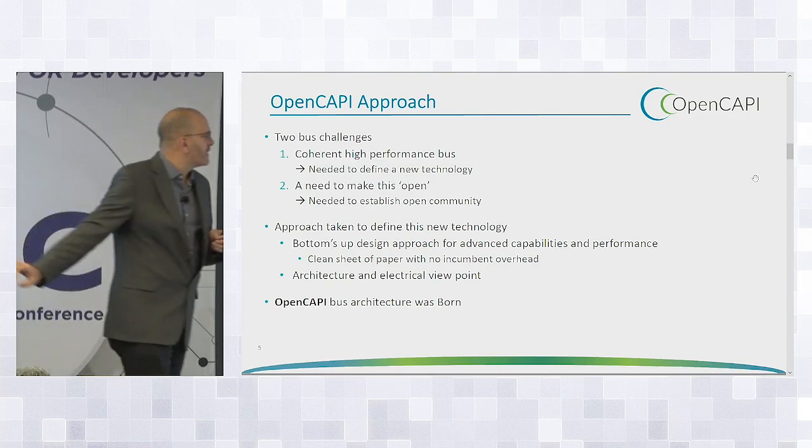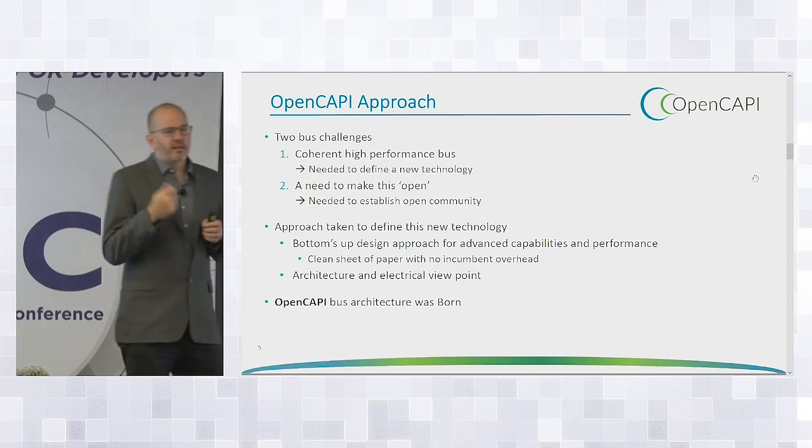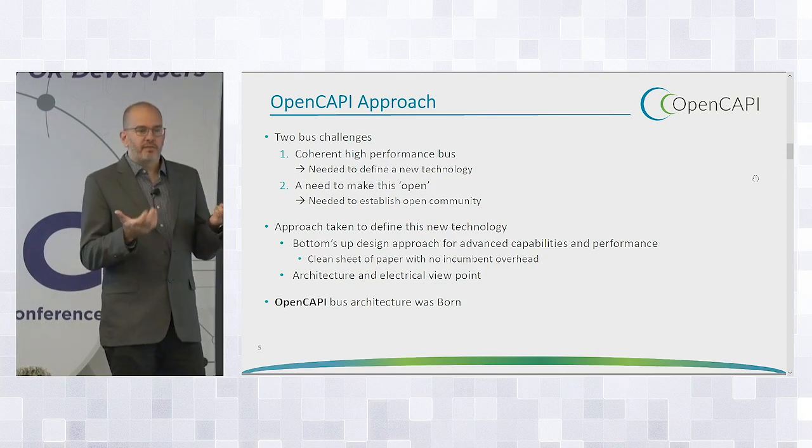The one interesting point though, just a side note, is the electrical standard with PCIe is actually fairly reasonable. It's a differential signaling interface. It runs at fairly high frequencies. And we've found that the electrical signaling with PCIe is actually quite compatible with OpenCAPI. So a lot of the vendors we've talked to currently have a PCIe-based NIC, whatnot, are able to take that same I/O interface that talks PCIe and have it run higher frequency and then talk OpenCAPI.